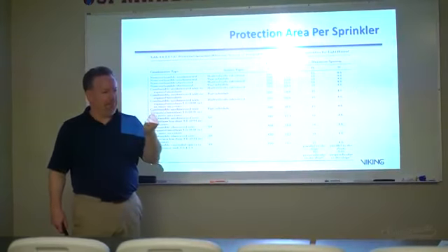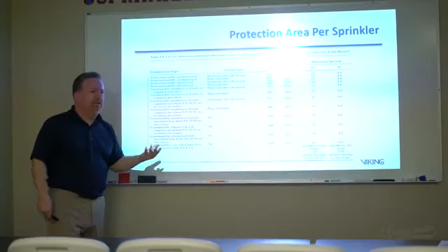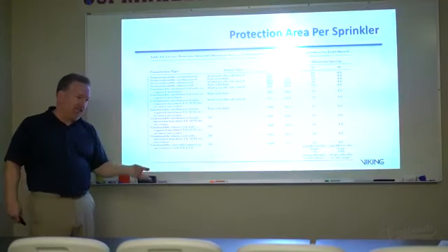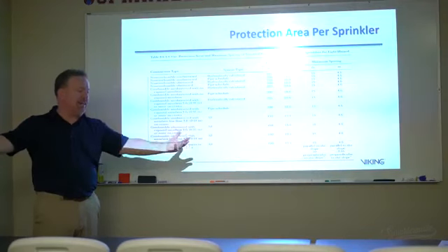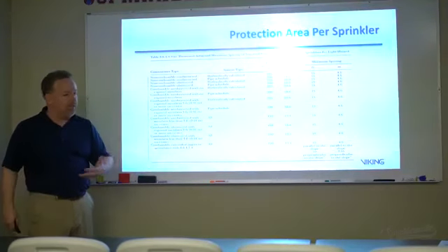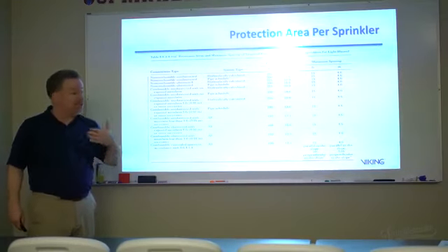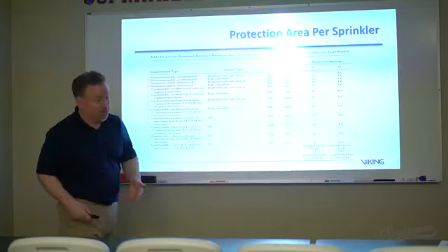Less money and get more coverage. Fewer sprinklers installed usually means a less expensive system. The challenge is that in order to get that extended coverage, you're probably going to need to have greater pressure. Okay, so it's not just a free-for-all. Otherwise everybody would be doing it.